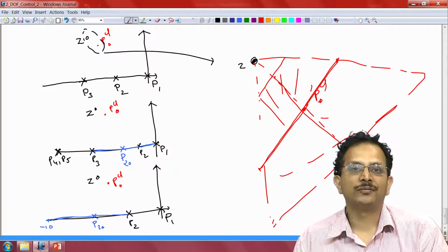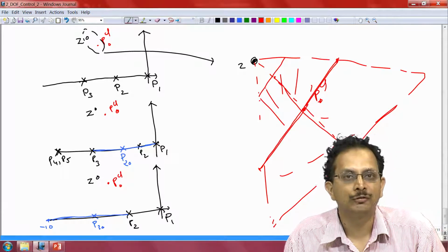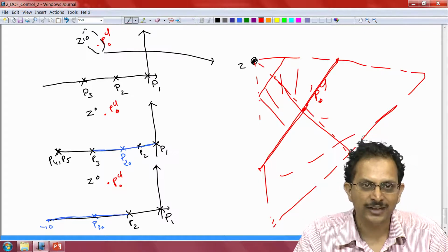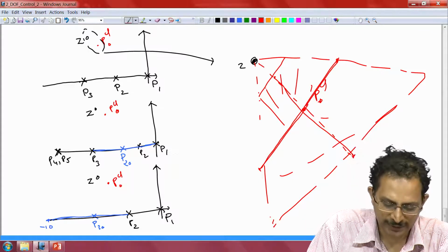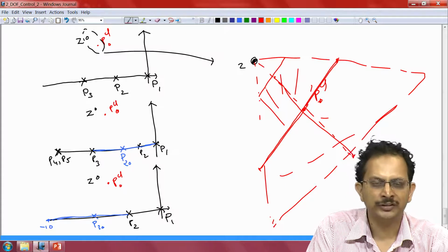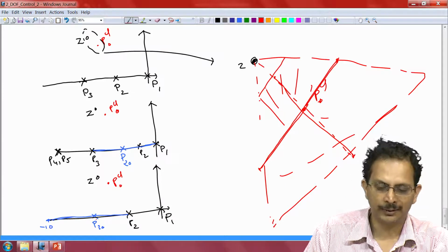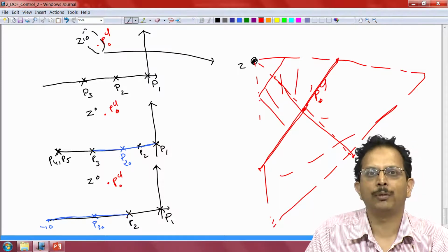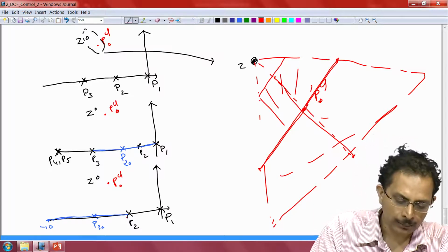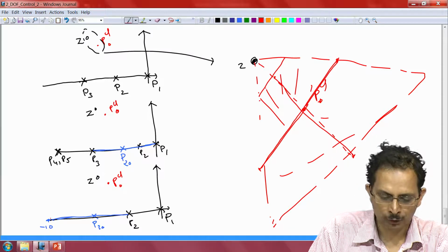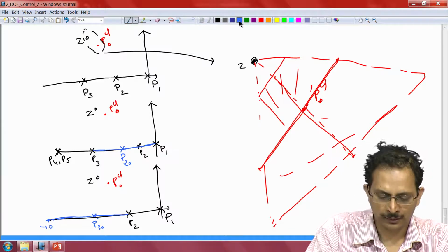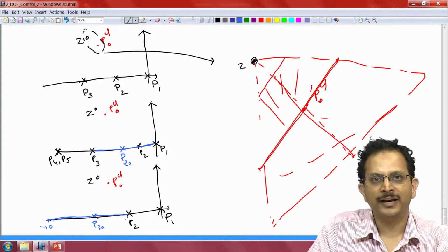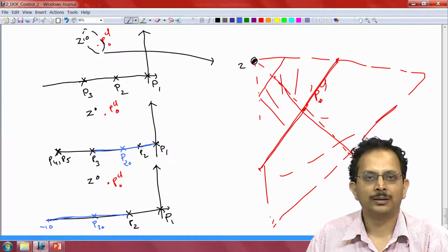Now, suppose we have the other pole also varying. So, suppose we have the pole P3 also varying as has been stated in this problem. It is nominally located at P3 naught, which is at S is equal to -2, but it can vary from S is equal to -1, at which point it will coincide with the point P2, and S is equal to -10. So, in the third graph here I have indicated with this blue line the range over which the plant pole location can change.